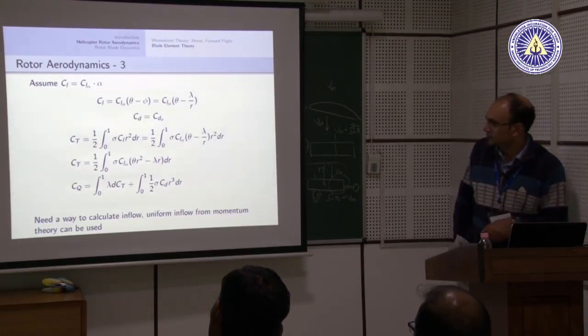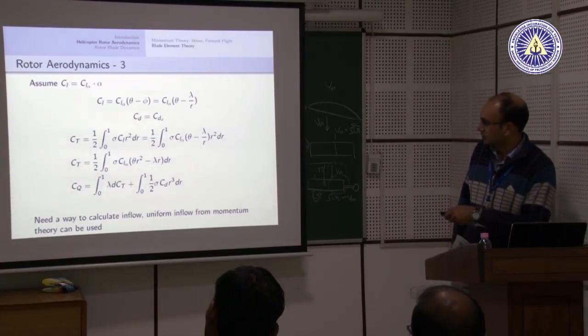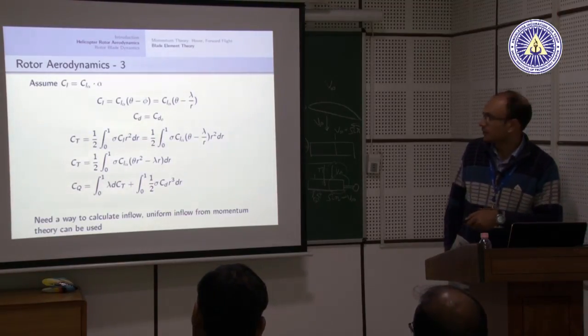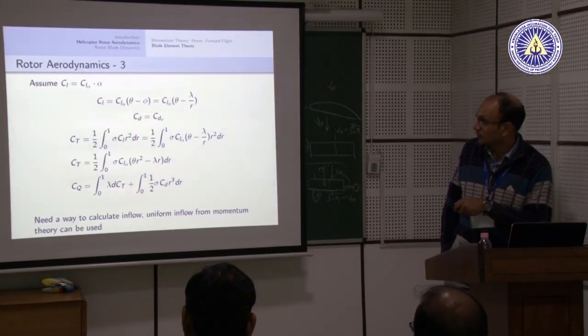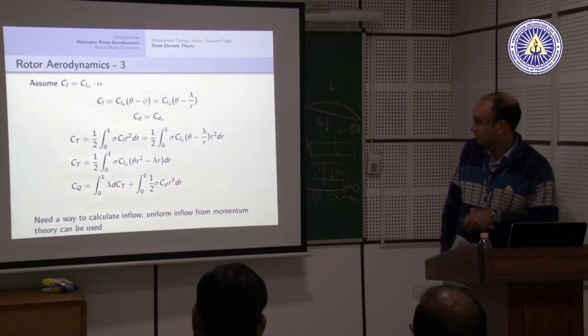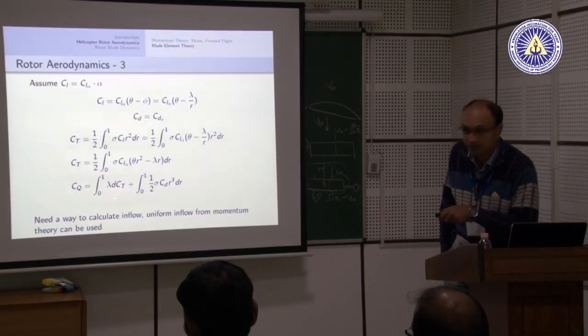You will see when Dr. Kothari talks about the core rotor, the variable pitch core rotor, he will probably start with these expressions, and he will find a relationship between CT and your pitch angle, because that is what we are interested in. This theta is my control input, and it is inherent inside this CT.